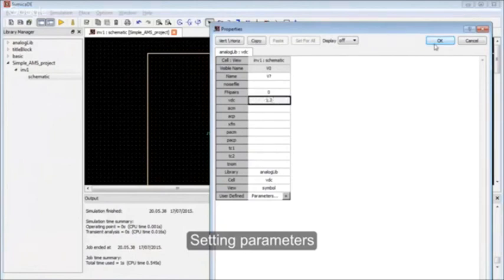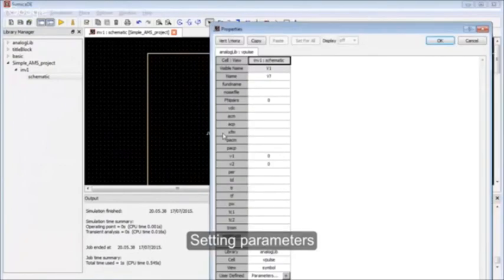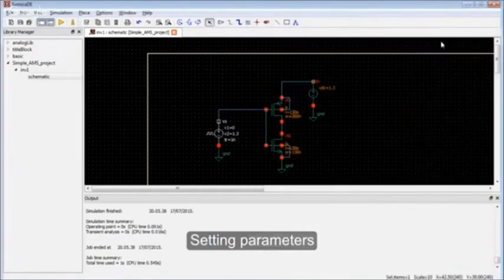We define the voltage source. We are making the pulse source. Here we are also making the same pulse. TD means delay, TR means rise time, then fall time, pulse width, and pulse period. And now we simulate.